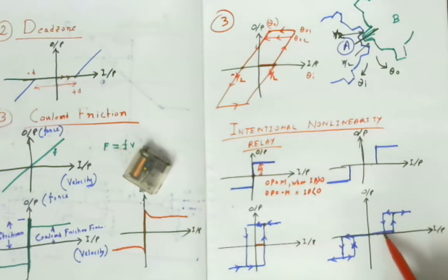So I am still increasing the voltage to the energizing coil. At 5 volt, the relay is now on. The energizing coil is energized. The relay is on, and after that point, if you still increase the input, it stays on. Now, if you decrease the voltage from 5 volt to 4.5 volt, 4 volt, up to that point, the relay coil is still energized.